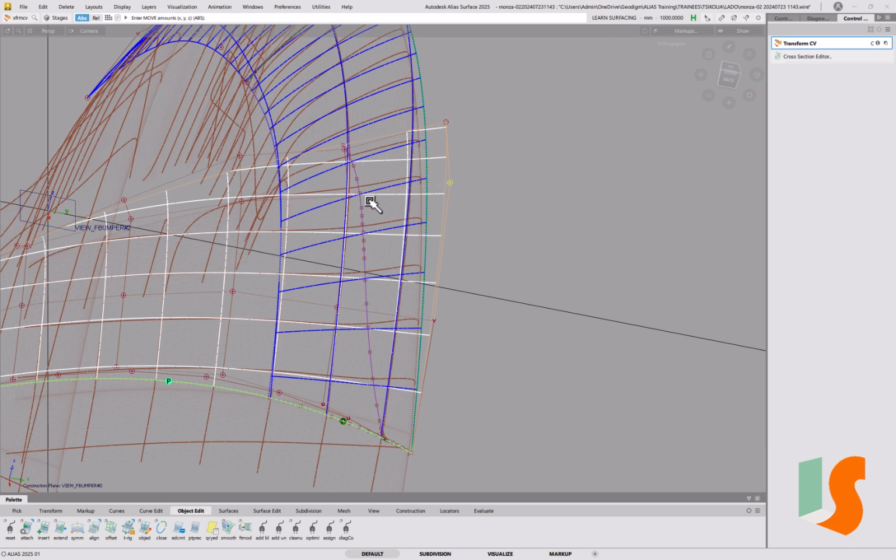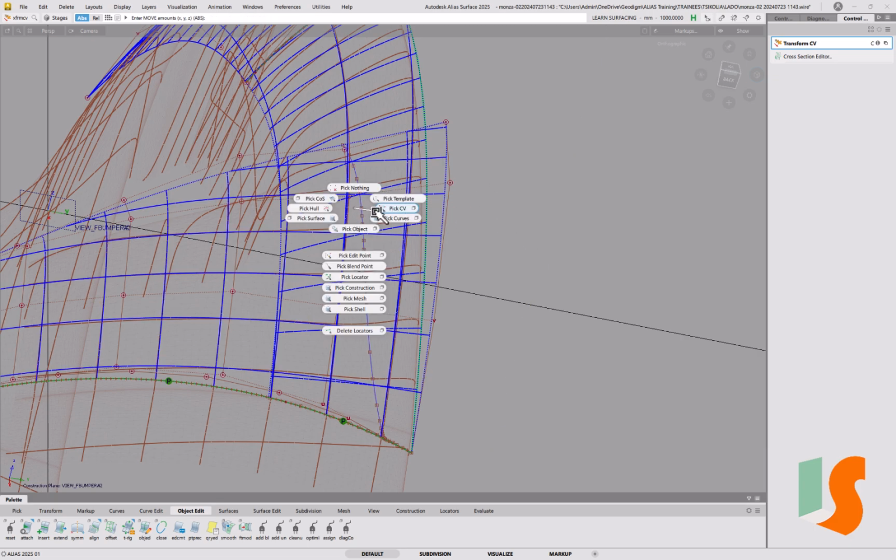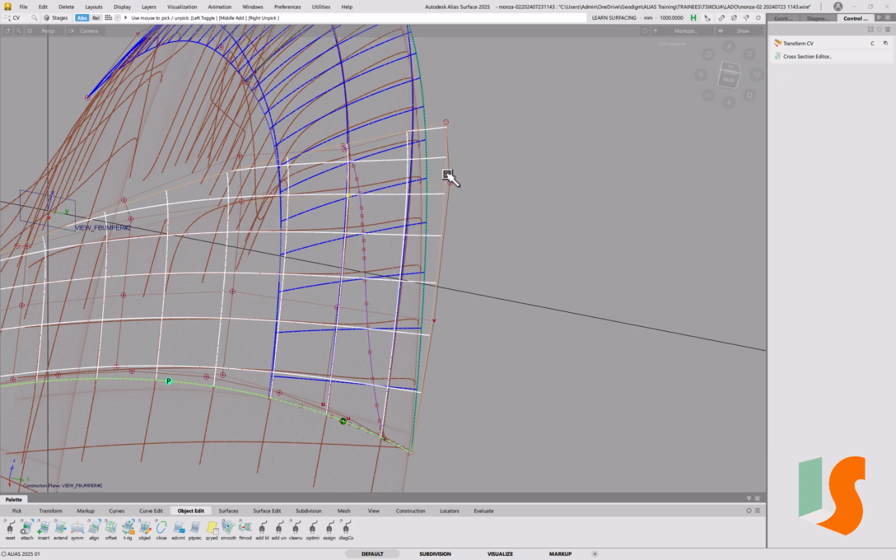So this one actually, difficult to see the CV there, but there's the CV there. So that's starting to, that's S-ing, in fact, which is what we want really, because that point has dipped below the line, the imaginary line that joins those two together. The same with that one. It is actually doing the right thing.